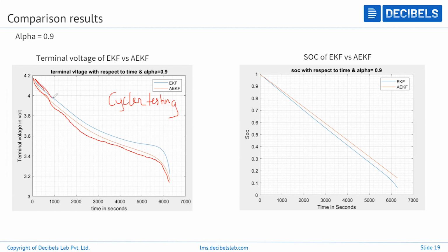I got the voltage curve, right? With your Kalman filter model, that is the EKF based SOC estimation, you also estimate the terminal voltage. So once you get the terminal voltage from your model, you try to overlap it with the machine data. So how much they overlap, how much the deviation shows. With that, you can start one step for the validation.